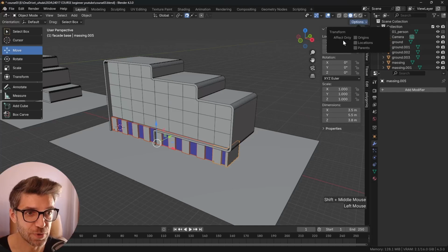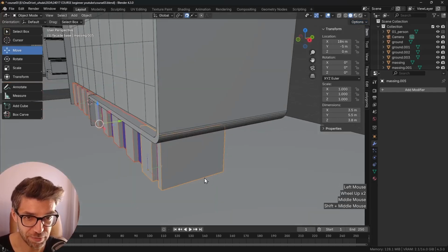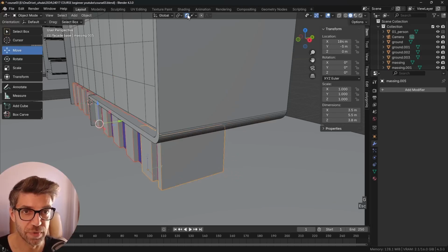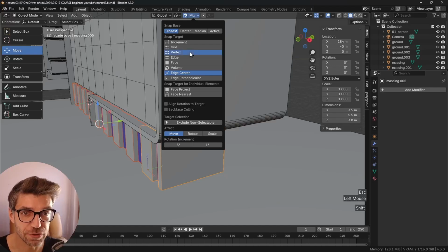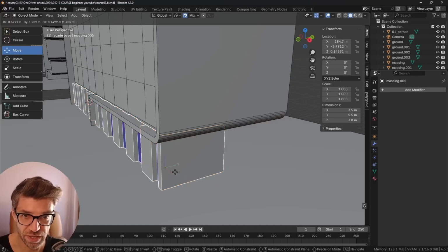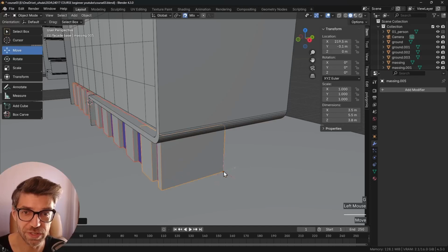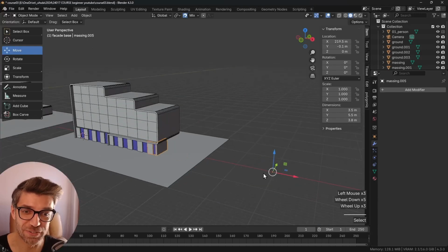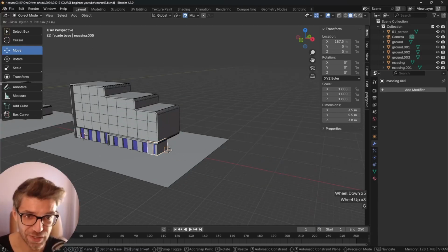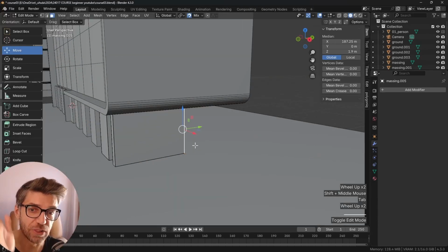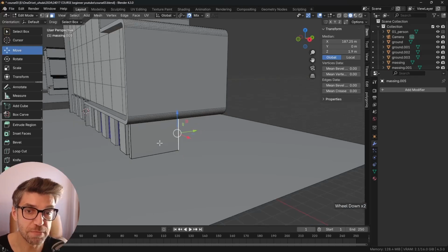Now we know how to move origin points. So we just go in here and snap. So G to move it. And let's make sure. By the way, we can shift click to have multiple of these. Let's try this again. G. And I never tried to move two vertices at once. I don't know if they're going to snap at the same place or not. Oh, they do. Nice. Oh no, they don't. That one is over there. So they're keeping their relative location. That's fine. So now they're all exactly at this point, and along that axis is where we're going to mirror.